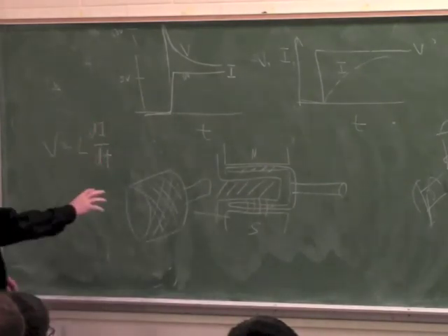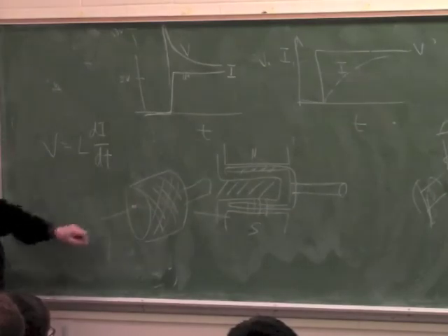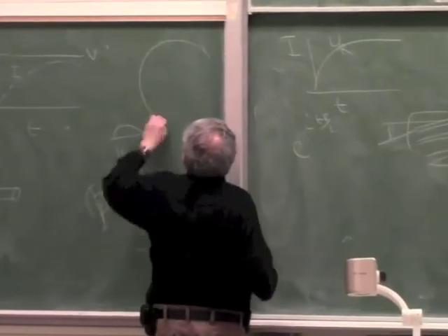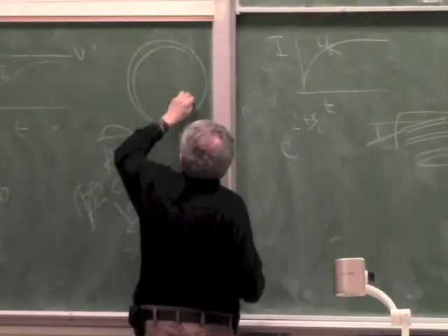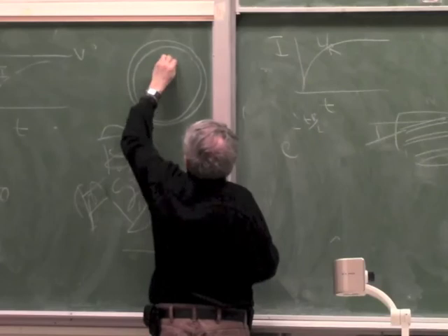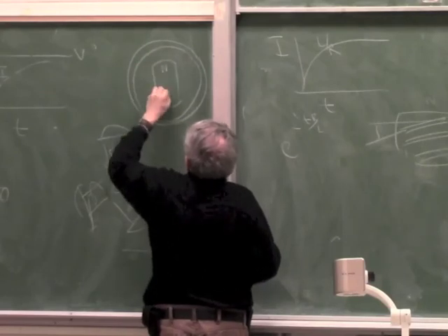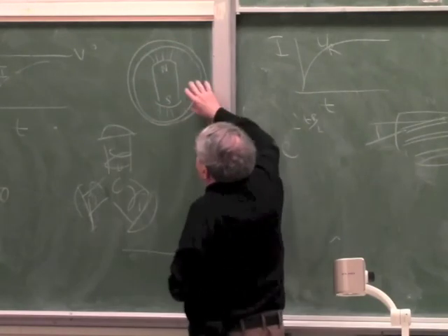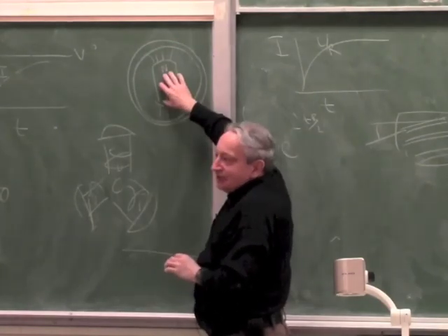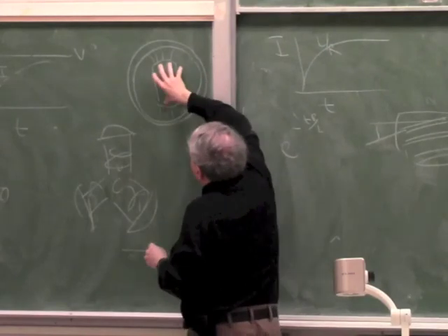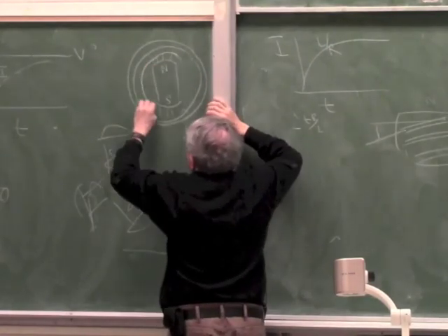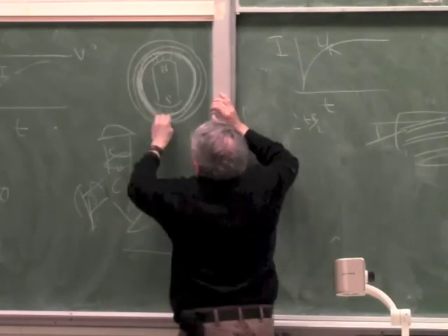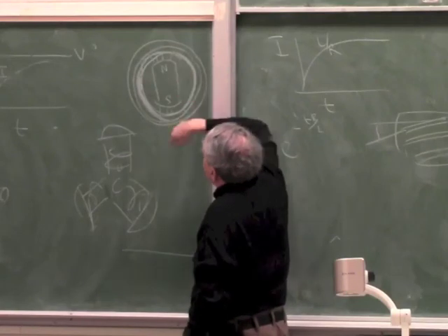Okay, so if I look at this motor from this side, I'll draw it here. I see a steel ring which is just to close the magnetic flux. Now I see a permanent magnet which is sitting inside and closes the flux to the steel, but this magnet doesn't rotate. And then I have a cup which goes in here. So this is a cup, okay, and this cup has a winding on it and has a shaft from one side, and it rotates in the air gap.